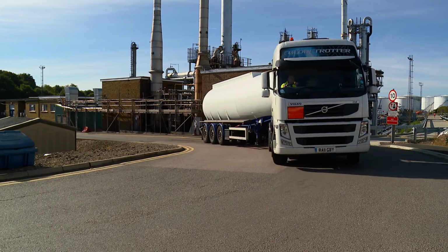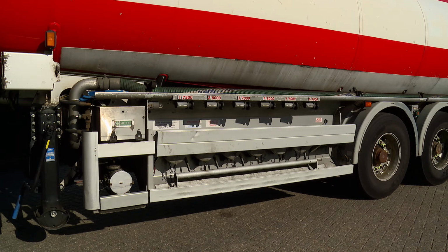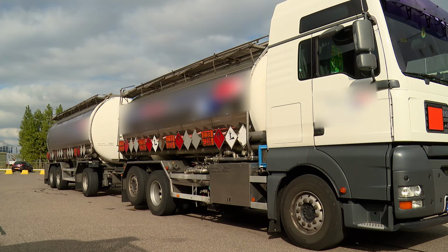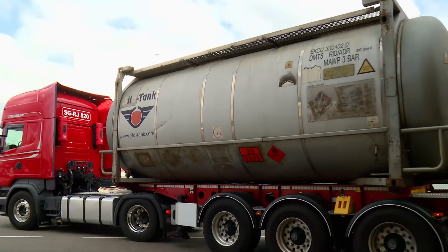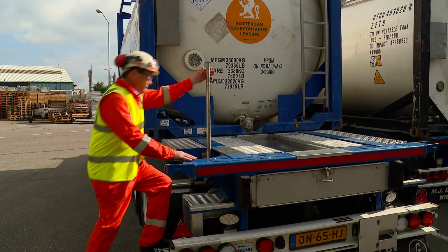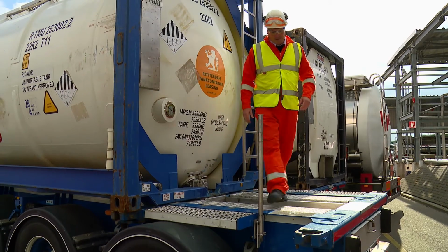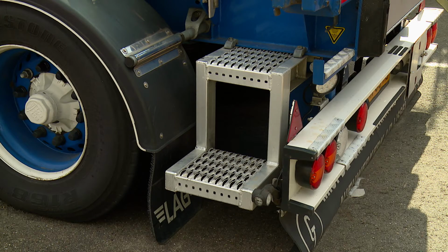Trailers for transporting solvents can be of single or multi-compartmental design, carrying a number of different solvents on the same vehicle. It is vital that the correct solvent is loaded into the correct compartment and is labelled as such with details of the associated hazards. If the vehicle is carrying solvent for a delivery in continental Europe and beyond, it is likely that the trailer will be a single compartment ISO tank. Procedures described in this film also apply to ISO tanks, although additional controls for the connection of hoses at the rear of the vehicle need to be adhered to in order to avoid working at height.